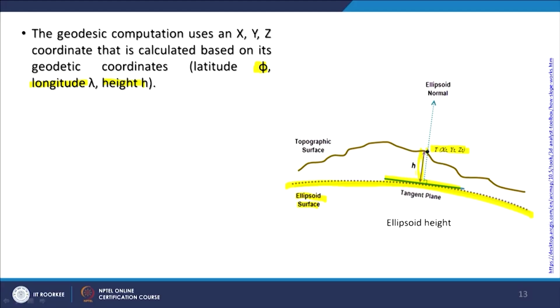If it is coming from the earth center, then definitely it would be the ellipsoid normal, otherwise not. That is why in GNSS you get variations; you expect something but you may not get the accurate elevation value. Though for XY, that is in a 2D system, that issue is not there. Generally, the coordinates in GNSS systems you get very accurately.